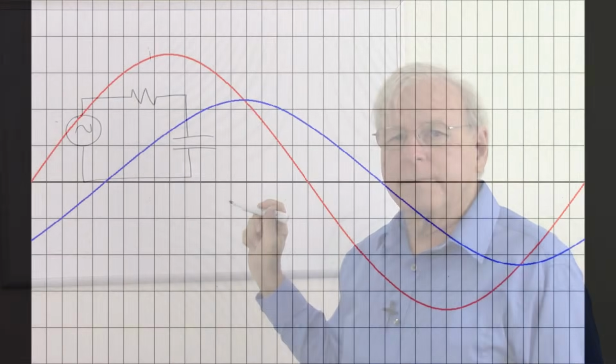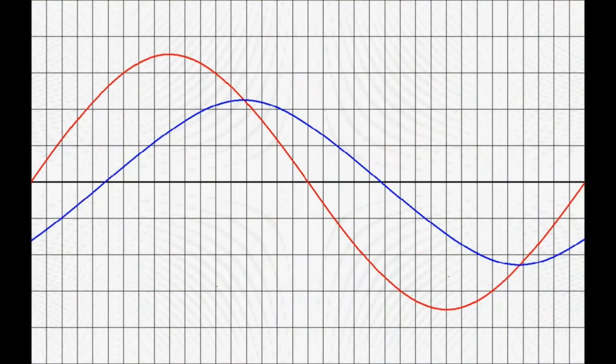and so the voltage across this resistor is constantly changing. In the AC circuit, the source voltage and the capacitor voltage are constantly rising and falling. These voltages are not synchronized, so the voltage across the resistor is continually changing. This means that the current is constantly changing. The timing of this change is related to the source voltage and the capacitor voltage. Let's look at these voltages at different points in time and see what the current is at those times.